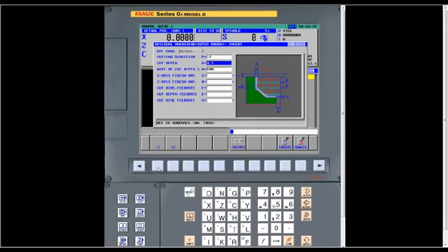Again, it's got Z minus, Z plus, and it looks just like a rough turning cycle, exactly the same fields. And the software will actually then go take that tool in, the one that will actually fit into that profile, and go in and just take out the stock that's left. So that's residual machining. Again, as I said, it looks exactly like the other cycles. Just fill in the blanks.